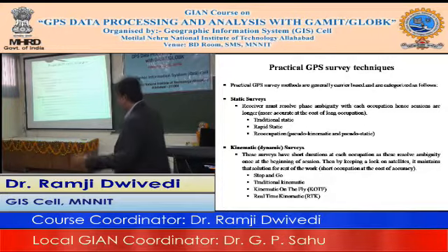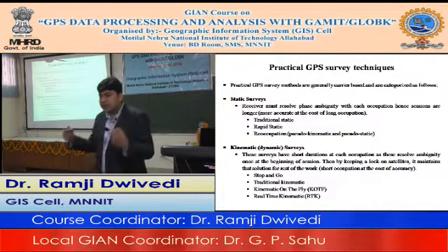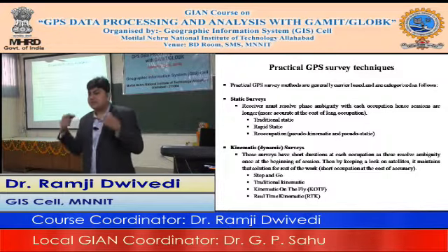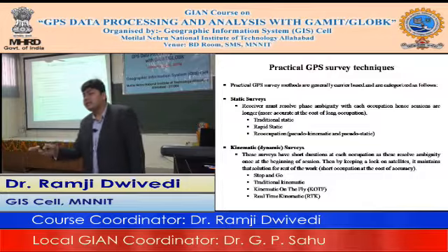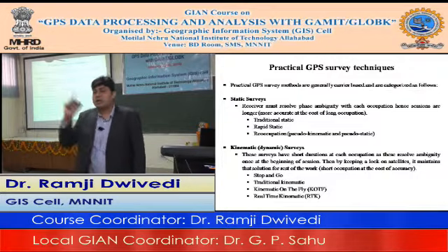So we call it stop and go, traditional kinematic, on the fly, OTF, real time kinematic. These are the words used when you apply correction in real time in the relative sense. So the mode we call real time kinematic is similar to DGPS, when you are providing the corrections in real time.